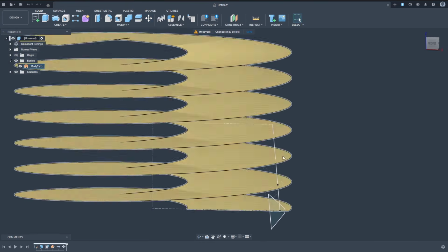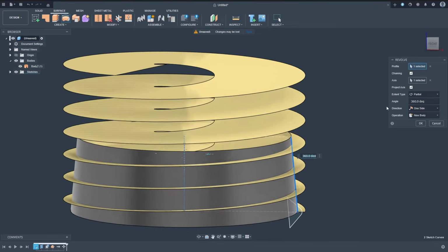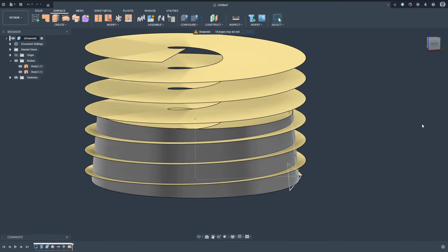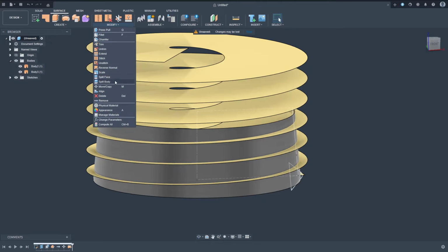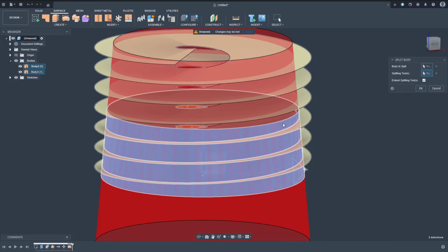Now I use the taper line to create the cone. From the Surface tab again, I use Revolve for that. Now what I really need is the intersection curve of these two surface bodies. I can create this by splitting the helical face using the cone. So I select Split Body before selecting the bodies. I want the Extend Splitting Tool option to be checked.